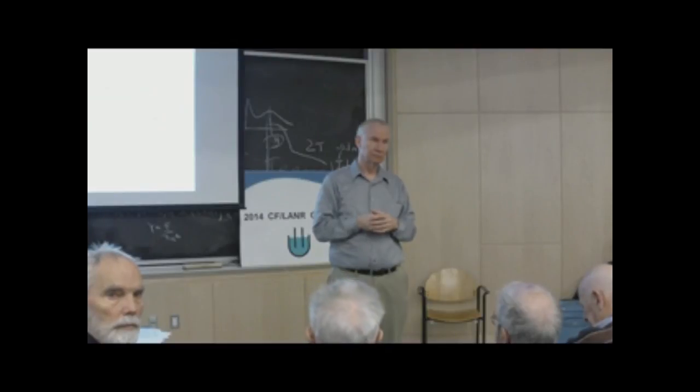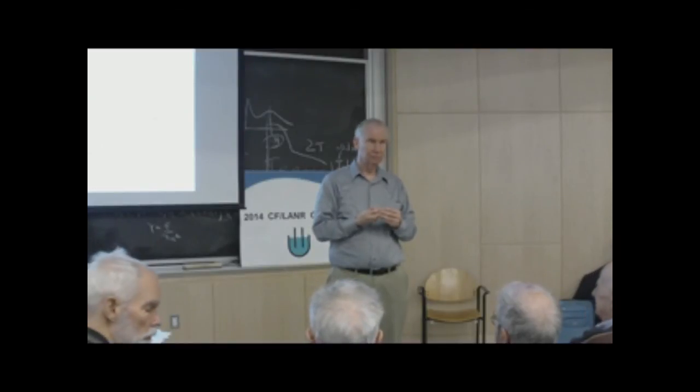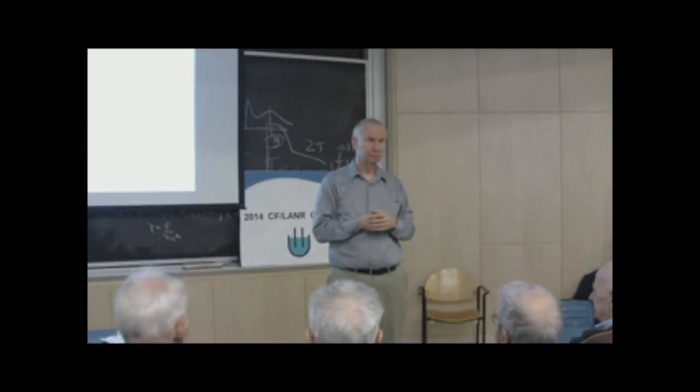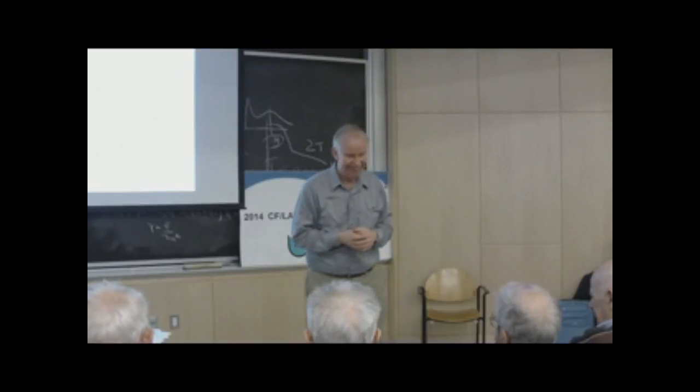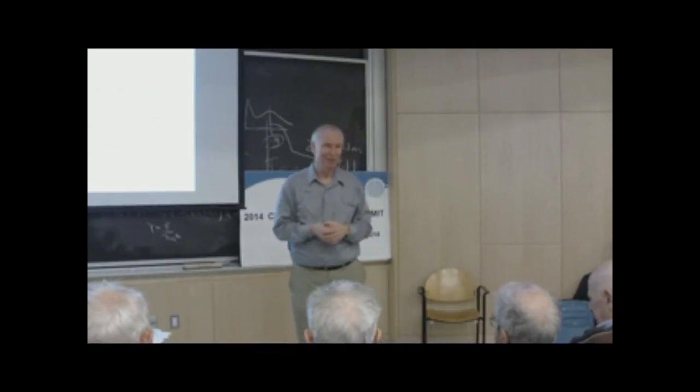So if you're vibrating this stuff or hitting it, you are essentially opening and closing cracks. Now it's going to etch the grain boundaries in copper. I don't know about the other elements. Aluminum and copper will react quite strongly at the boundaries. So you've actually got a fracture experiment in your vibration. We'll try to follow up.